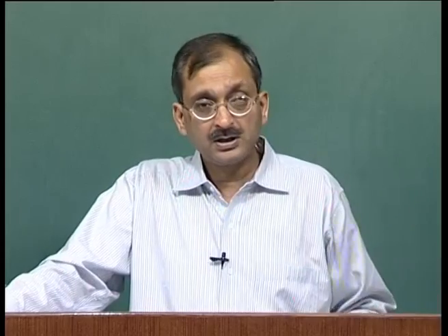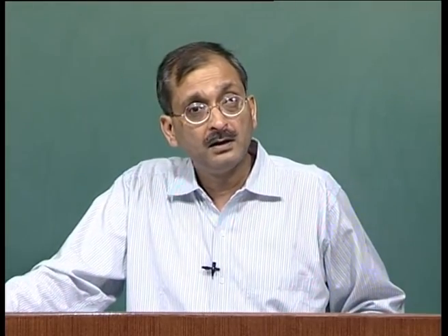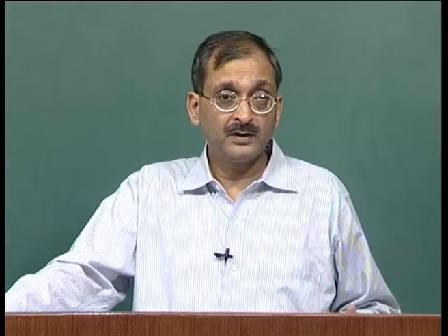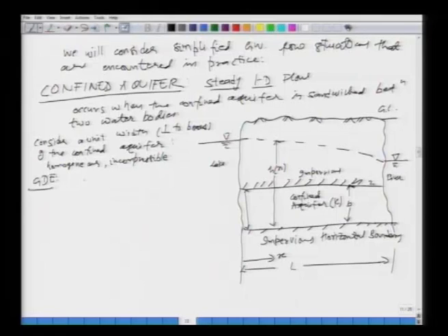We just saw that this is a Laplace equation, which was del 2 h over del x square plus del 2 h over del y square and so on. But we have only one basic dimension, flow is taking place only in x direction. So, what will be the governing differential equation? Well, Laplace equation in x, only one dimension. So, you have del 2 h over del x square is equal to 0.